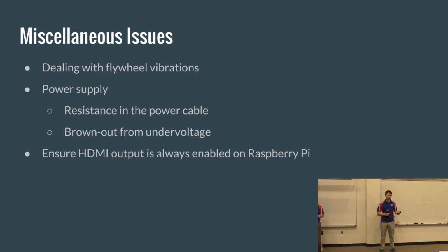So if you don't have force HDMI on enabled, you need to make sure you have it plugged in and your TV or whatever you have it plugged into is actively searching for something on that port when you turn on the Pi, or else you'll have issues. So turning that on saves you a lot of trouble in the long run. I would do it first thing whenever you get a Pi and you're planning on using it.